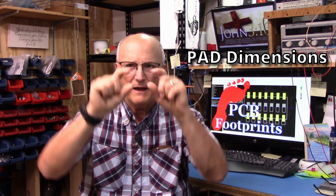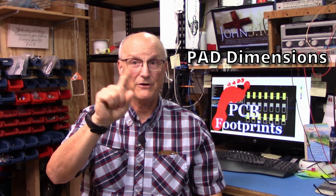So what is it that we need to know? We need to know the size of the pads, in other words, the length and the width of the pads. Now with some parts, there could be some pads that are required to be different sizes than others, and I'll talk about how to do that a little bit later in this video.